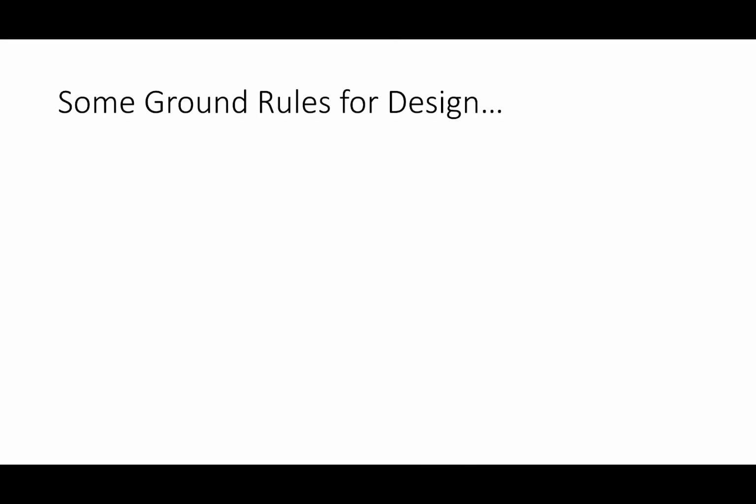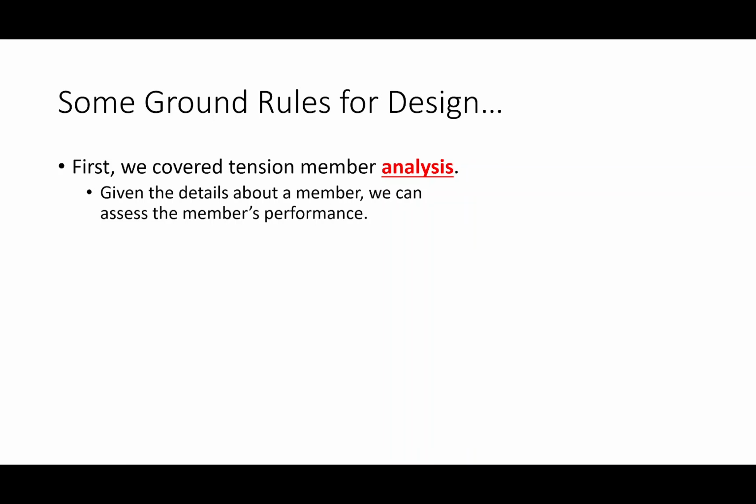So what do I mean by design? Well, maybe what I should do is start by saying, what do I mean by analysis? What I mean is I give you details about a member, and your job is to assess the member's performance. Here is a W10 by 49 with 3/4 inch diameter bolts, spaced 3 inches on center. It is subjected to a dead load of this, live load of that. How is it going to perform? So you factor the loads, gross section yielding, net section fracture, compare them, compute efficiencies, slenderness check, all that. That is analysis, okay? If you want to call it assessment, that's fine.